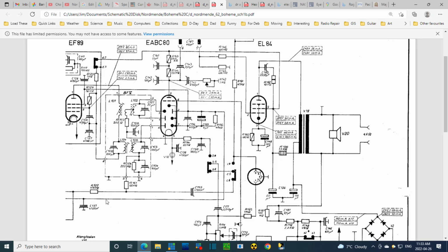No. No, it's just feeding the eye. So all that's happening is you're taking a little bit of voltage off the detector here and using it to operate the eye. It's not actually controlling the input earlier in the radio, the radio's sensitivity. Very different systems. Different source of voltage, and everything's different.